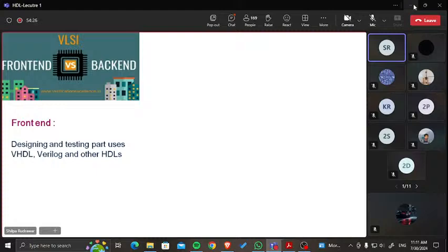Then for checking the correctness, because I have written a counter, but whether it is working properly or not, functionality wise, whether it functions like an up counter, down counter, and loading is happening properly or not, I need to test. Testing is very important, isn't it? If the hardware is with you, it is called testing. But whenever you have the design in soft form, it is called verification. Is it clear? What is the difference between verification and testing?